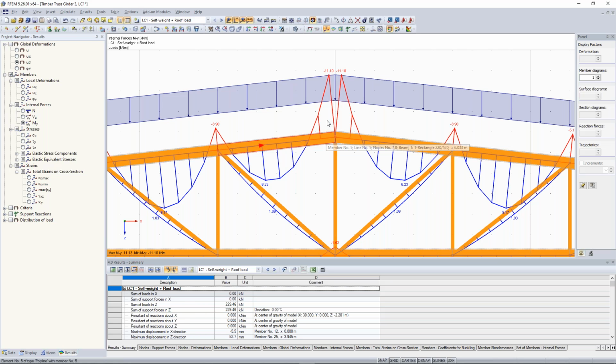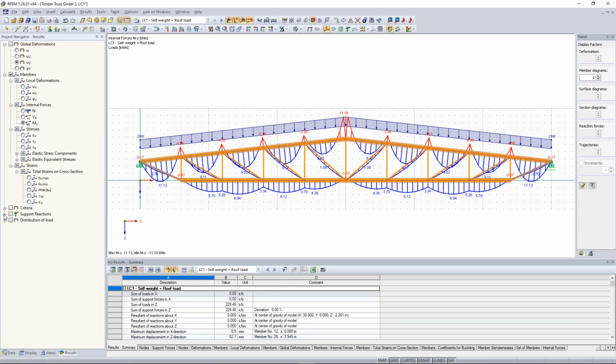And then also check the support directions. Last check, support direction. Are they the same on the left and on the right side when I have a symmetric load and also a symmetric structure? Yeah, in this case we have the same vertical load.